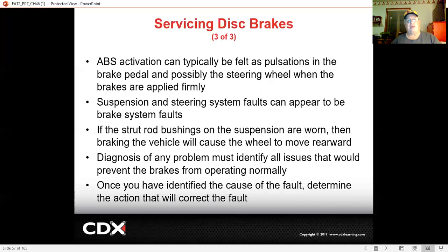As it applies and releases the brake, when it's released, you do have some steering input. So it can be very helpful for that. And also, when your brake is sliding and it releases it and then reapplies it, there's a chance that it will grip better. So ABS is a good thing, and most everything out there has ABS now.